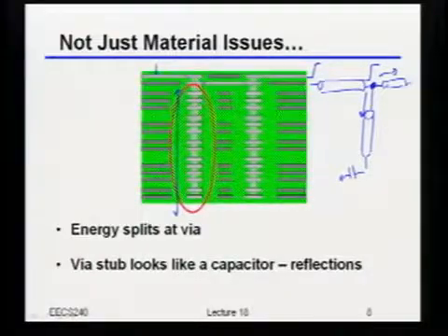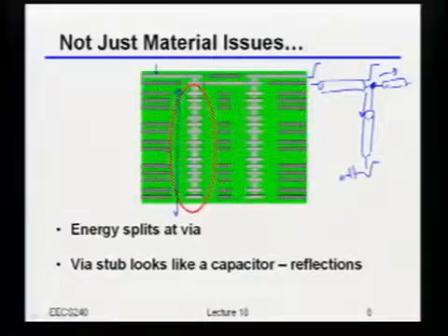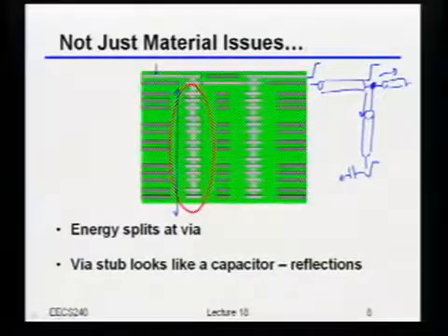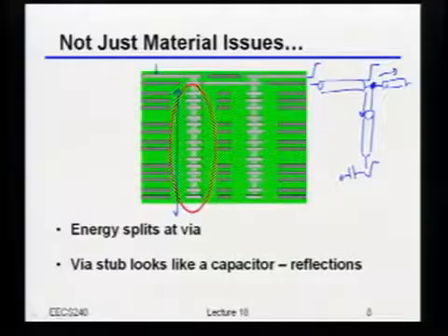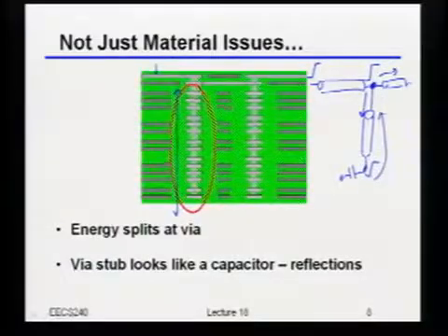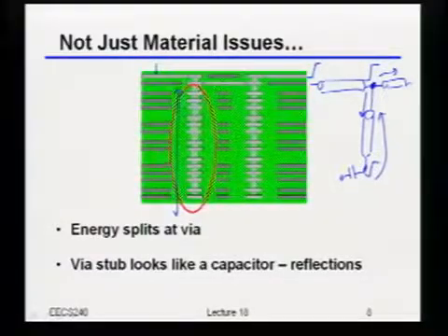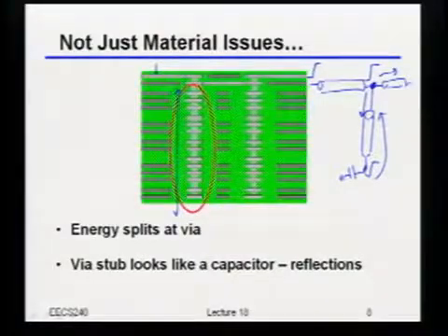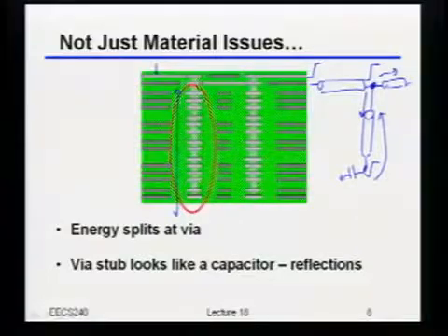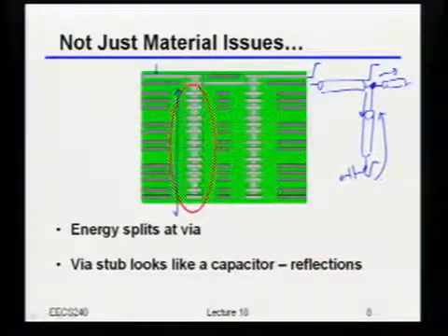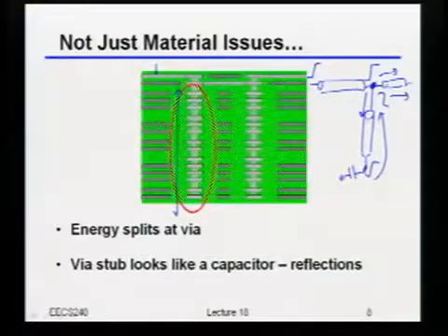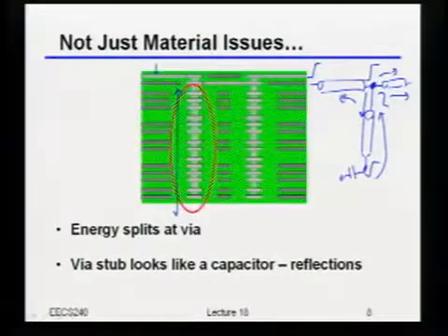Well, so then once that step shows up at the via cap, hey, you can't change voltages on capacitors instantaneously, right? So actually, initially, that wave is going to get completely reflected back. Once it reflects back, of course it'll come back with the opposite phase, because it can say, hey, no, wait a minute, you can't actually put voltage here. And you can imagine now it's going to come back over there, and the negative step is also going to propagate over there. Of course, it's also going to go somewhat over there.